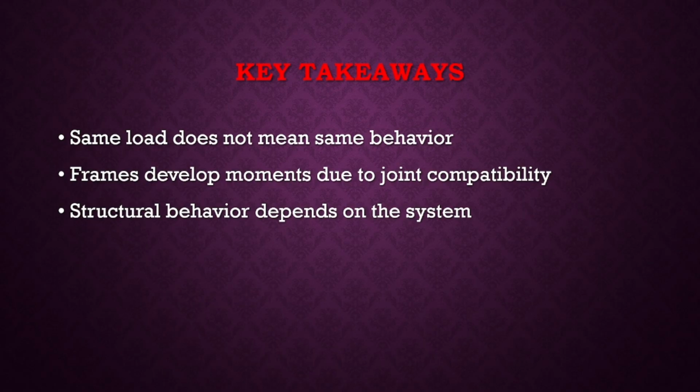So remember this clearly: the load did not change, the beam did not change, only the structural system changed. A beam is an isolated element, a frame is a connected system, and once elements are connected, they must rotate and deform together. That compatibility is what creates bending moment in frames. If you understand this difference, you will stop guessing structural behavior and start predicting it. This is real structural engineering.